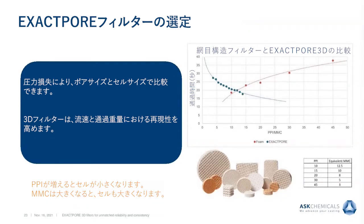flow rate. The samples of pore size and MMC were put on the chart to create a trend line. If you look at the red line, which is derived by the foam samples, you can see that not many of the foam samples actually touch the trend line. This is due to the inconsistency of the foam process. The blue line, which is the EXACTPORE line, has nearly every sample touching the trend line. It just shows the repeatability of the 3D process over a foam filter.